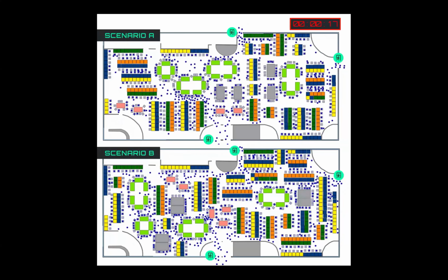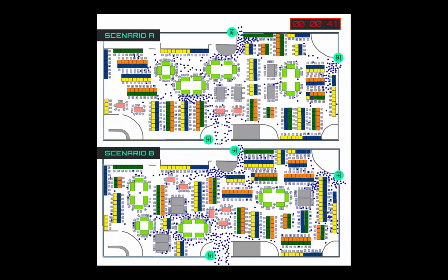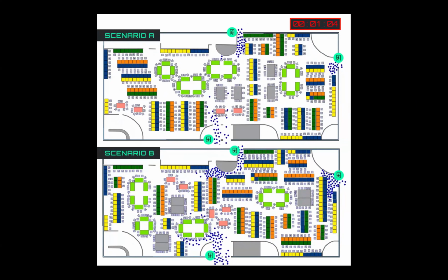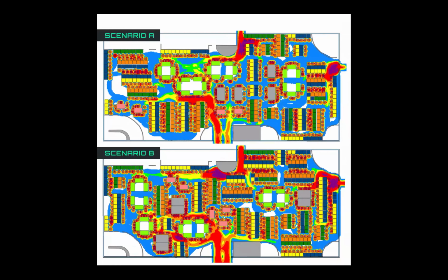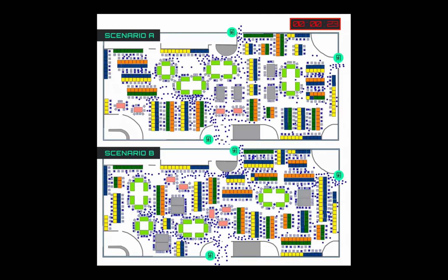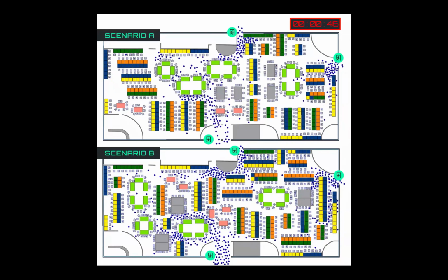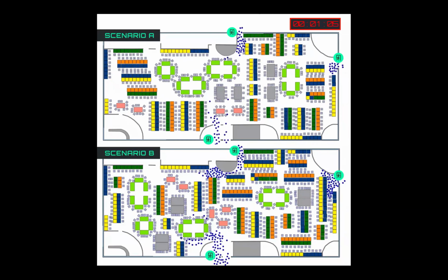In smaller scale environments with many obstacles, like in a casino here, simulation can also provide answers to questions such as which layout is more efficient and ultimately safer during an evacuation. We saw here a density overlay. That's, again, a fantastic feature that PD has. This is showing us graphically where the crowding is occurring in different layouts, and it does help us inform which layout is superior. The results also showed us which layout had the fastest evacuation time, so you have 2 angles to look at it from when evaluating these 2 layouts.